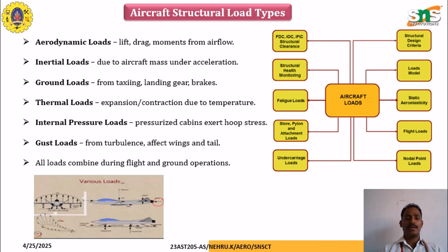So generally in aircraft, the loads include aerodynamic loads, inertia loads, ground loads, thermal loads, internal pressure loads, and gust loads. These are all due to the existence of drag, lift, and moments as flow passes over the external body of the aircraft, and due to the aircraft maneuvering under different velocity or acceleration.